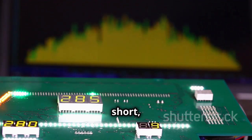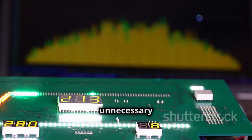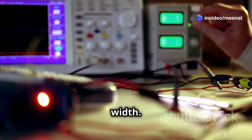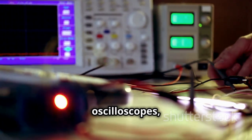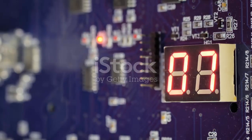If the pulse is too short, the system may not reset correctly. If it's too long, it could cause unnecessary delays. Let's see how to determine the optimal reset pulse width. By analyzing the system's requirements and using tools like oscilloscopes, you can fine-tune the reset pulse to ensure optimal performance.